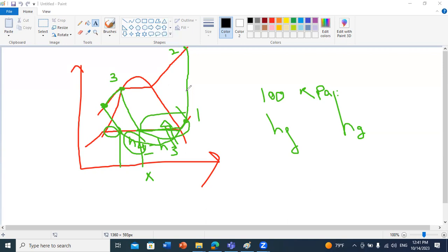And from the properties of points, of course, I know that you might forget how the throttling valve will operate, that H3 equals H4. So in case I want to give you anything new, I will remind you in the problem. I will tell you in the throttling process, assume the enthalpy will not change. But I just consider that, of course, you know how the compressors, the evaporators, and the condenser operate. Then you will be able, from the given, to build your diagram and then to answer all questions after.